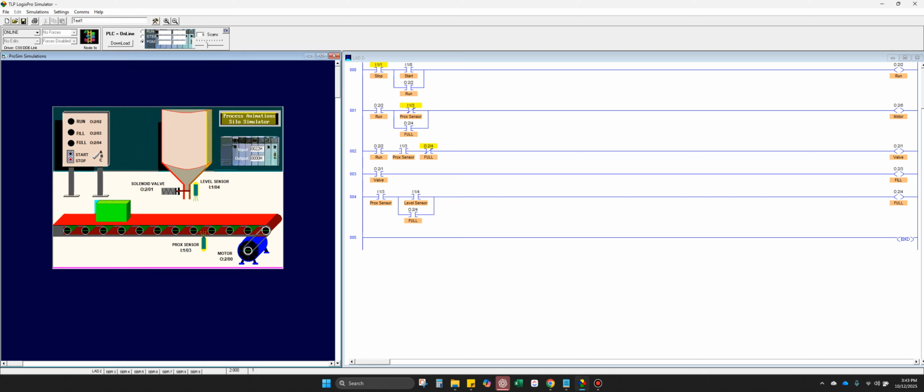And this rung is to control the motor, which is actually the conveyor. And the conditions are when the light is on, run, and when the proximity sensor, which is normally closed, and the full light over here is activated. These are the conditions. It's normally open, and the run is normally open.